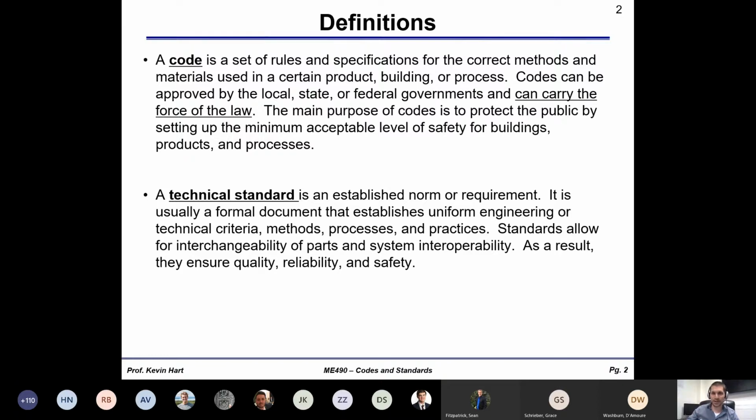All right, that would be 20 threads per inch or 28 threads per inch. Those are sort of standardized bolt sizes that people have generally come to use and understand. And so there are documents that detail, okay, if you're going to have a 1/4-20 bolt, this is the standard size and how we make it, and all these sorts of things.